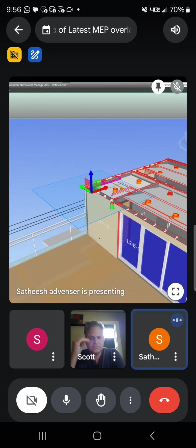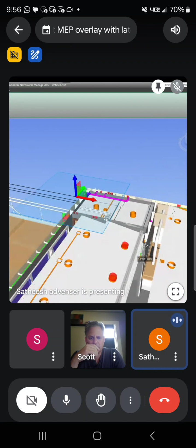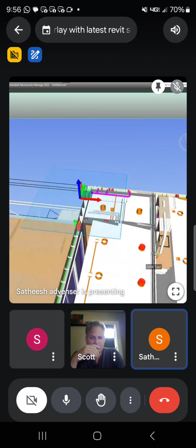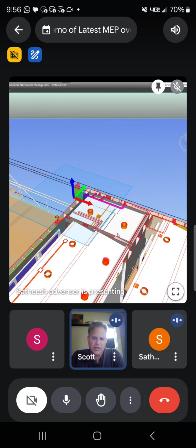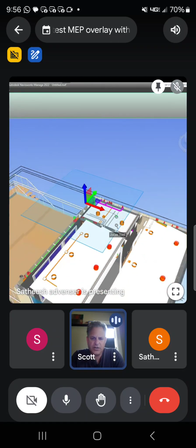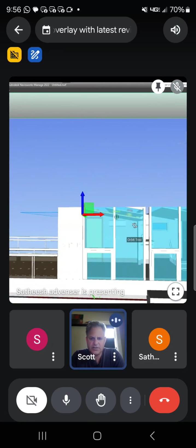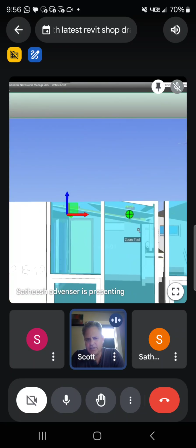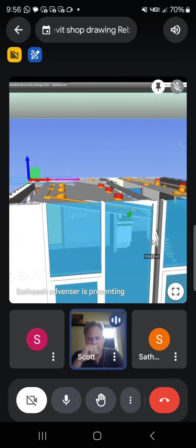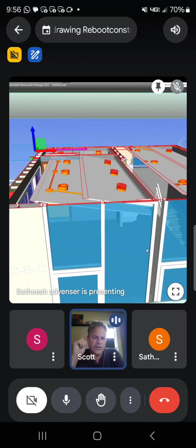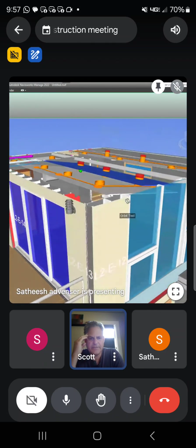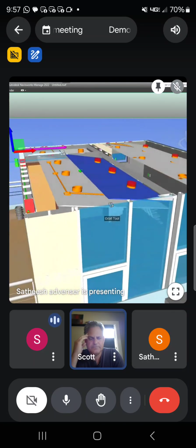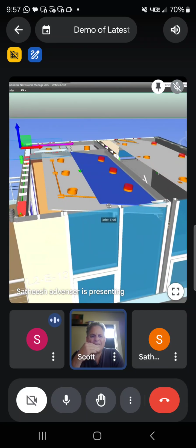I think in total, on ground level there are 2 restrooms and 1 kitchen, and then we have the upstairs bathroom. Then we also have a future sink area by the stairs there that's going to have another vent. I'll check on the code. That might need to be a 3-inch pipe coming up. I'm not positive. But is that the right place for the vent, Scott?